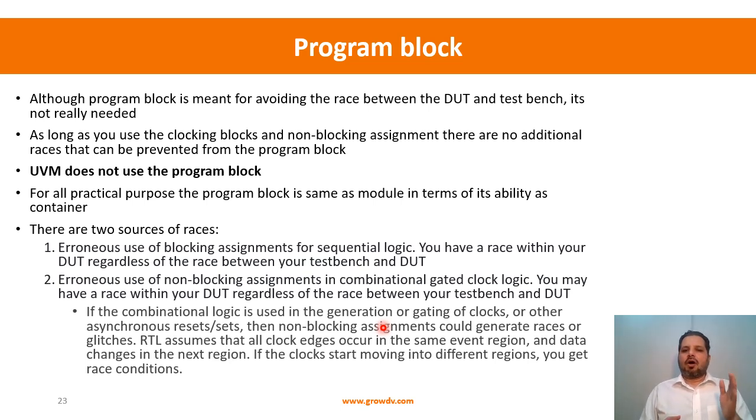Clock is considered as something that is expected to happen before anything you do in the design. Now, when you do the gated clock and use an additional combinational element in that, that fundamental rule gets violated. Now the clock changes again in the active region, because you have used combinational logic, and the clock itself can change, leading to re-execution again.